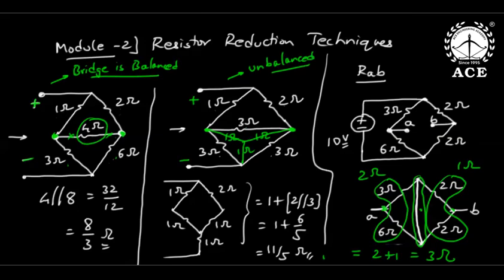Now the third is about finding resistance. Resistance is a passive electric property, so remove the active element. The active element here is a voltage source, so I remove it, short it. Then this becomes 3 ohms. Okay, now I am giving the next set of problems. I want you to write again.